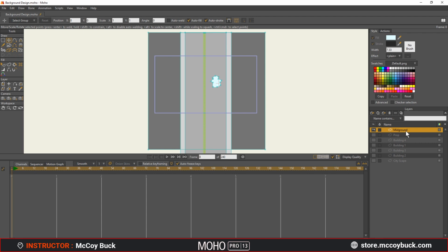Once the midground has been created, we are now ready to create our 3D scene. To get started, select the midground layer, then come over to the Layers tool panel and select the Rotate Layer XY tool. Then enter in the value of -77 degrees for the X rotation.